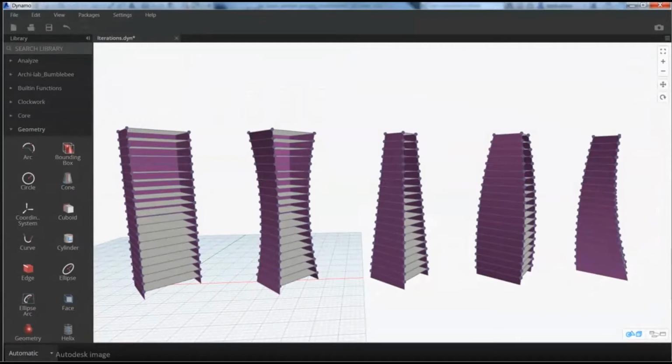And for those who have been using Dynamo for quite a long time, Autodesk added different nodes in Dynamo for Revit, such as Include Shadows, Include Embedded Walls, and Element.SetPinStatus, where you can set pin status like true to pin and false to unpin. That was added in the latest release for Dynamo for Revit, and also Autodesk added refresh capability to the Workplane Reference Viewer.